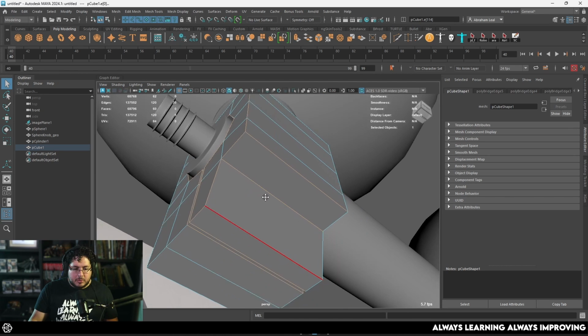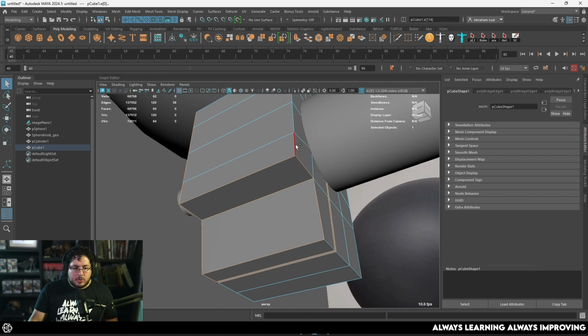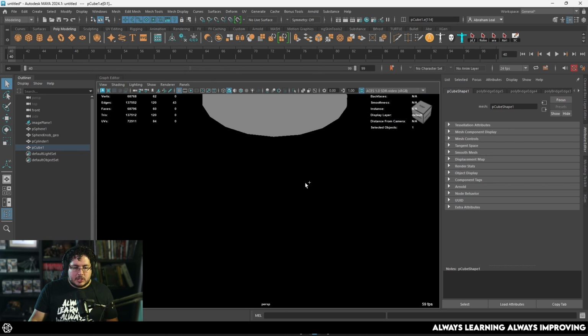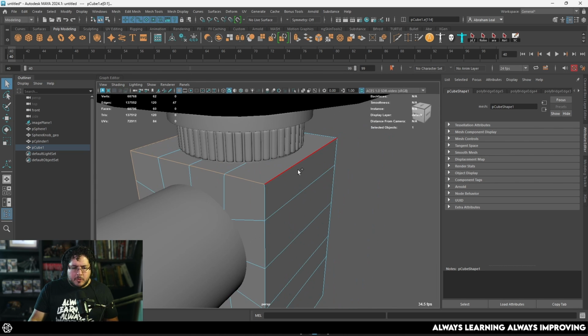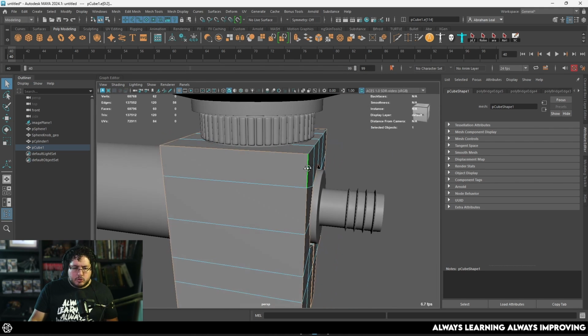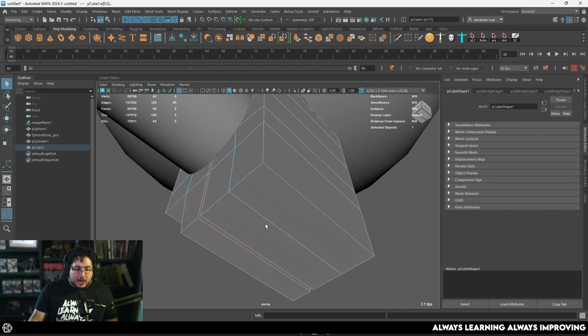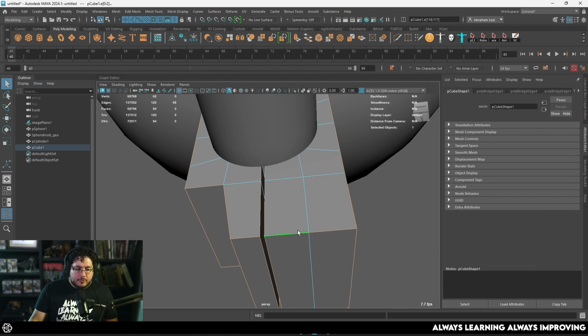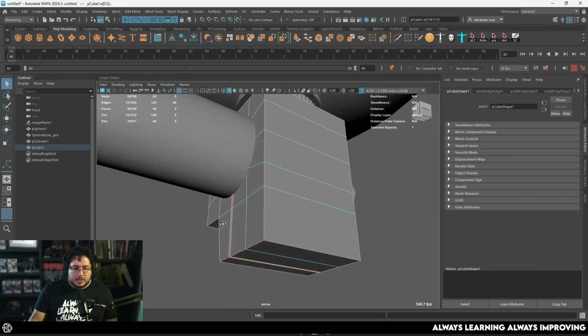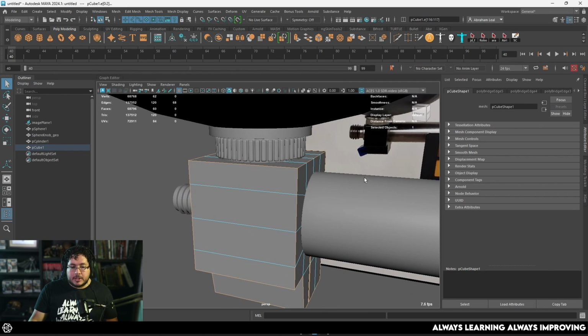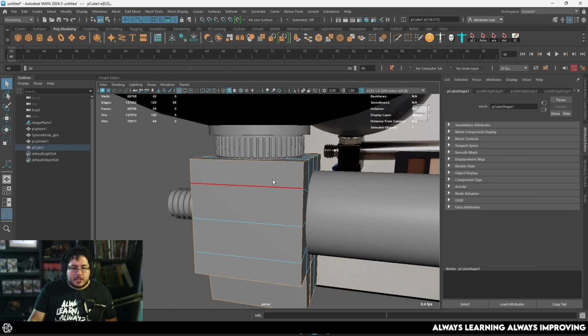I'm just going to do the bevel at this point, because it's a very, very square shape, very simple shape. Some of you might be wondering, why are we not adding support edges instead of doing bevels? Remember that support edges will give you a very hard, almost knife sharpness on the element, and a bevel will give you a softened edge. And this looks like a little bit of a softened cube.